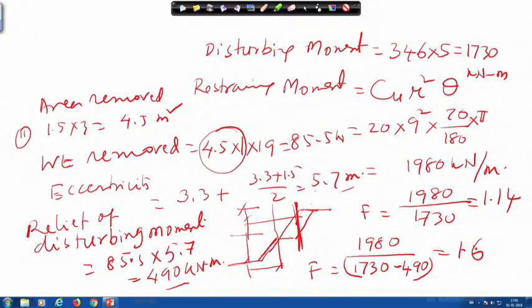When there is a slope, we find that it can be unstable any time. So, to make the slope stable, we can cut some portion from the top. Or sometimes if we have a steep slope, instead of making a simple slope, we can make a benching, that means, we can do small benching. If I consider from here to here it is quite steep, but if I go this way it will be quite a mild slope. That is the concept sometimes adopted in the field to have a better factor of safety. You can remove some portion from the top of the slope.